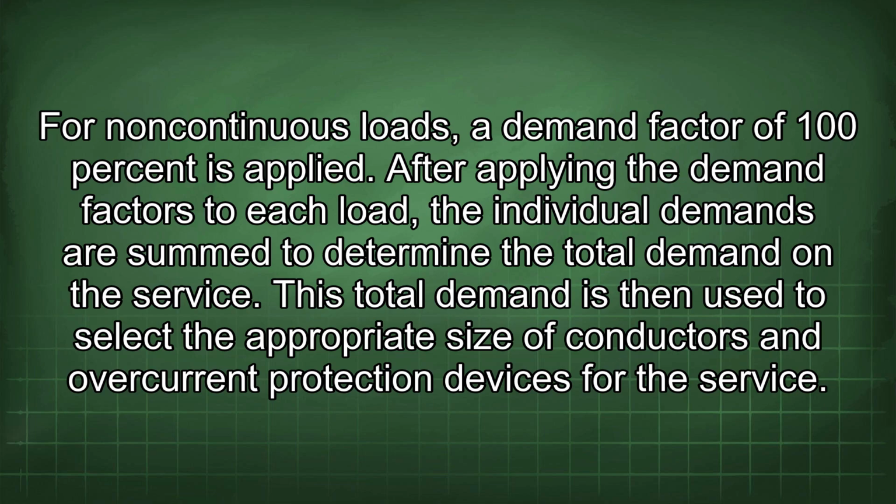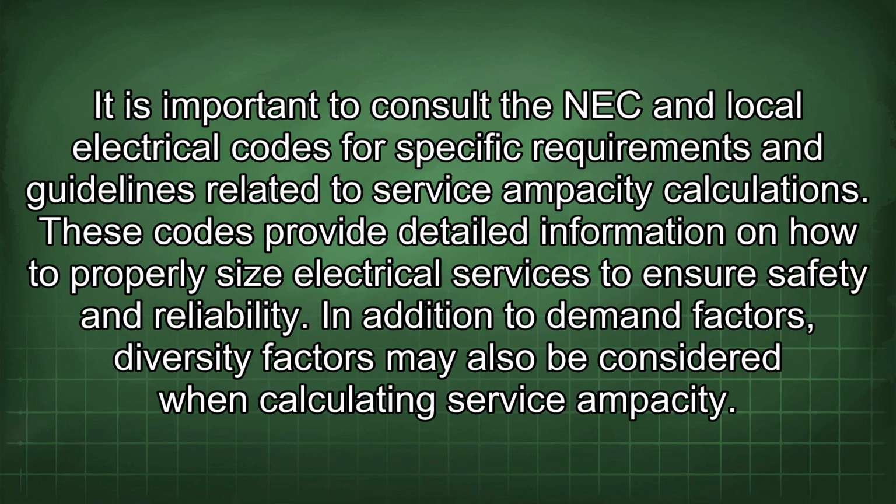After applying the demand factors to each load, the individual demands are summed to determine the total demand on the service. This total demand is then used to select the appropriate size of conductors and overcurrent protection devices for the service. It is important to consult the NEC and local electrical codes for specific requirements and guidelines related to service ampacity calculations. These codes provide detailed information on how to properly size electrical services to ensure safety and reliability.